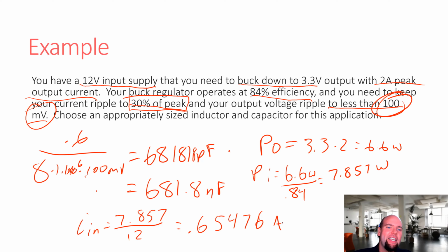It's also an interesting thing because if you look at cell phone chargers for your car, there's two types. Cell phone chargers that go in your cigarette outlet. Some of them are linear regulators and they get warm and they're very inefficient. And some of them are switching regulators. Nowadays, they're mostly switching regulators, but you'll still find some that are linear regulators and they dissipate a lot of heat. Because in a car, you're going from about 14.5 volts down to 5 volts for a cell phone charger. So if you're using a linear regulator instead of a switching one, that's a big efficiency difference.